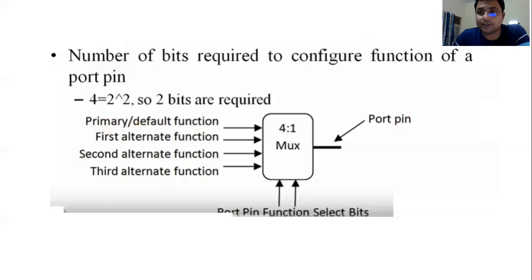All these registers, pin select registers and every subsequent register, are memory mapped. Our system comprises 4 GB memory. So everything is mapped inside that 4 GB. It is not a separate memory; register memory is not separate.